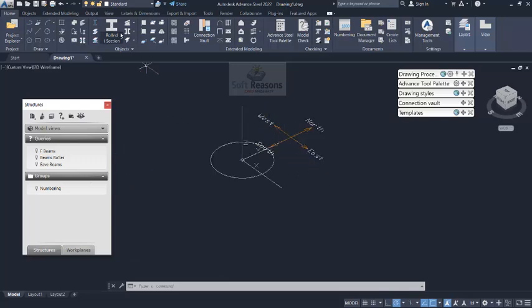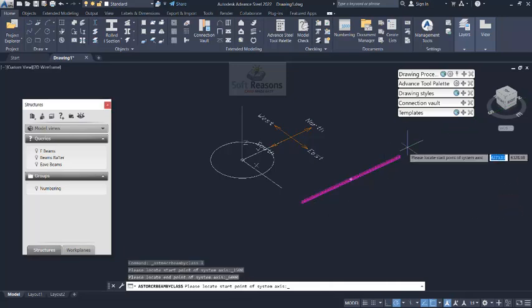Having said this, now I want to draw a beam with respect to these queries that we have set. So for instance, I'll pick this row I sections, and then I select this. Snap that point, move my hand toward these directions, and then we key in 1500 to get a distance from that point. I snapped successfully and press enter to pick that point. I get this way, so I may have a beam of length 6000 millimeters. Just type in 6000 and enter. So that is the beam.